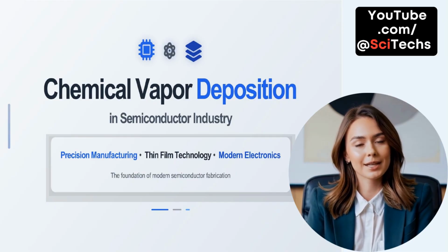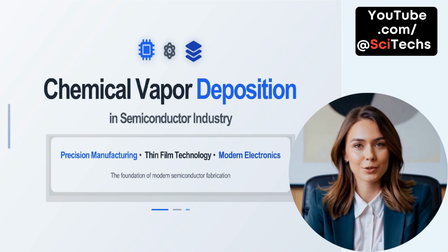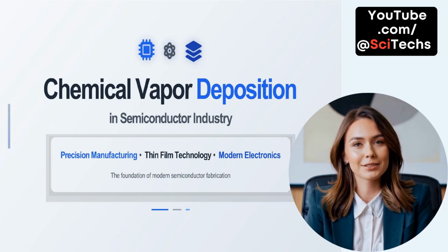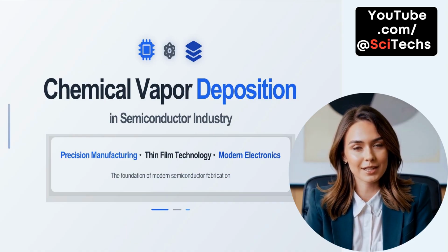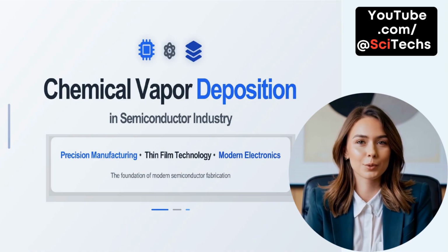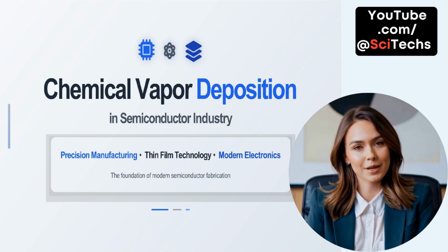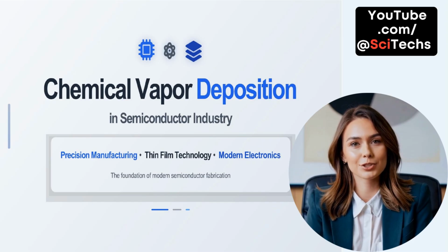With CVD, highly uniform and conformal films can be deposited on complex three-dimensional structures, a key requirement as devices continue to scale down in size. It is a cornerstone of thin film technology, producing materials like silicon dioxide, silicon nitride, and metal silicides that form insulating, conductive, or barrier layers on semiconductor wafers. Furthermore, CVD is indispensable to modern electronics, supporting everything from logic transistors to NAND devices and sensors. In summary, chemical vapor deposition is truly the foundation of modern semiconductor fabrication, enabling the advancement of technology across industries.